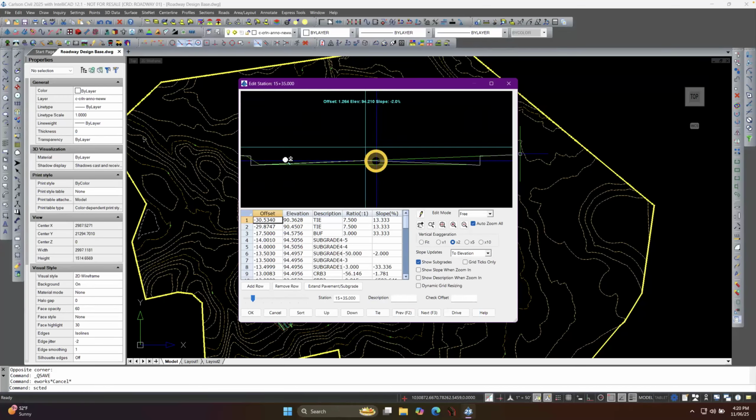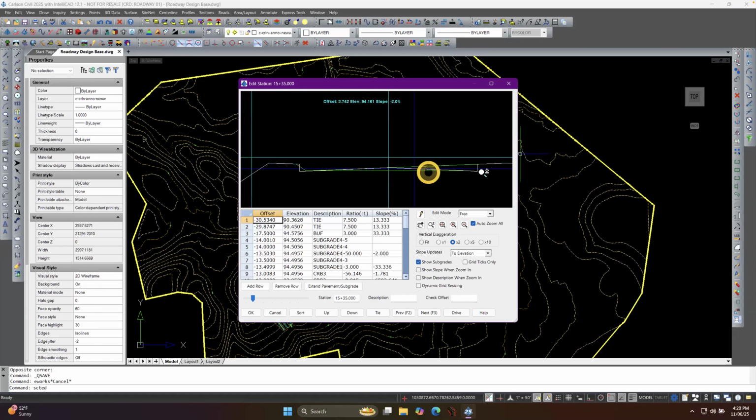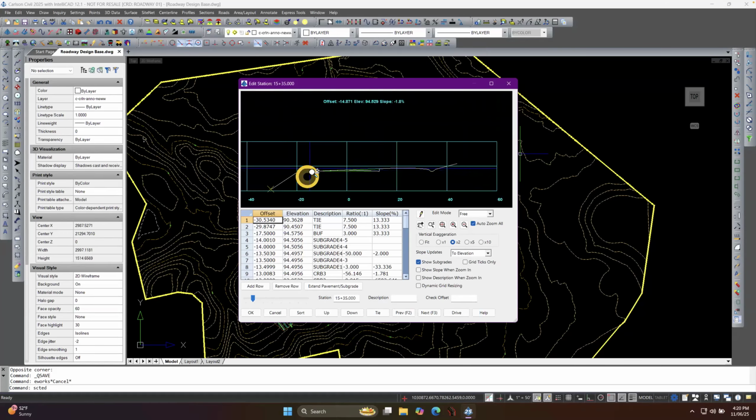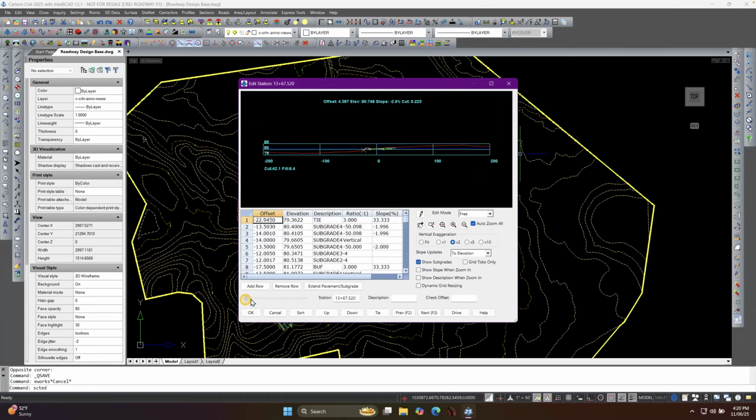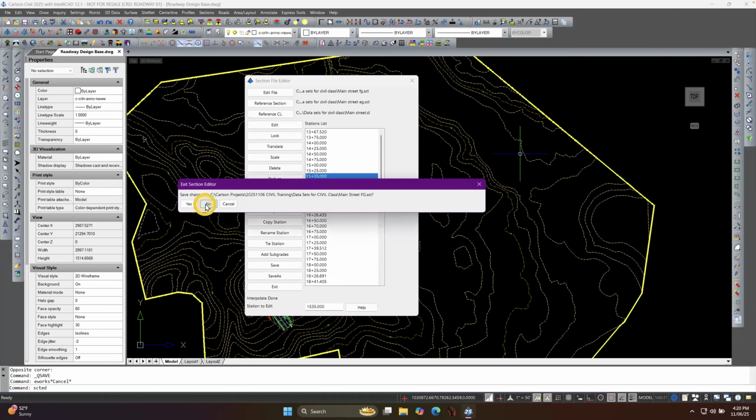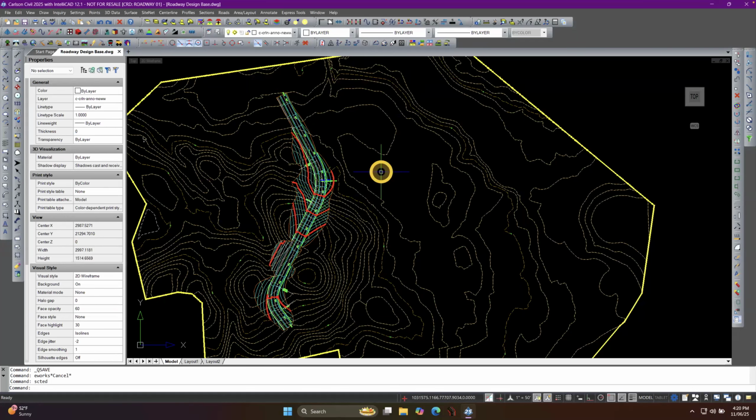And you can see it doesn't have all of the, it's just using that top surface because that was that finished grade certified, but it interpolated between those two stations, the 25 and 50, to give you that station value right there. Okay, so that's a useful function for seeing some of those and maybe even making changes to it if you need. But here's what is useful in their road processing.